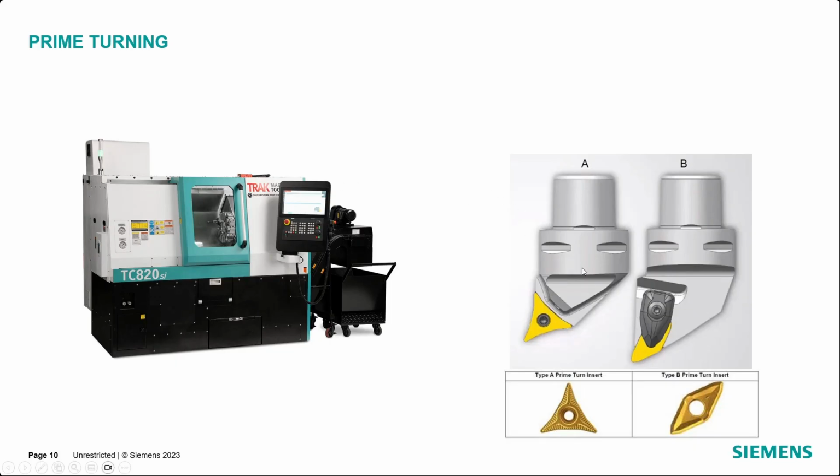Now I started out when this first came out to the market and did a lot of testing, and this is really proprietary to Sandvik. These are Sandvik inserts and Sandvik holders. And really, as an application engineer, being on a lot of projects, this really lends well to a lot of gummy materials. So your stainless steels are, I think, really huge because you're able to use a bigger part of the insert to create a lot of chips. And from those chips, you really can move a lot of material. When you're using these types of exotic materials, you're able to pull from it.